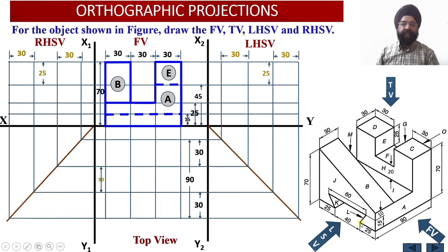Similarly, if this point happens to be 25 millimeter towards the back side, so this point which is lying on the top face of this slot over here will be lying 15 millimeters behind the front face of this particular solid. So with this information, now I am going to draw 2 projection lines over here, which are going to represent this point which will be 25 millimeter from the rear face, and this point which will be lying 15 millimeter from the rear face over here.